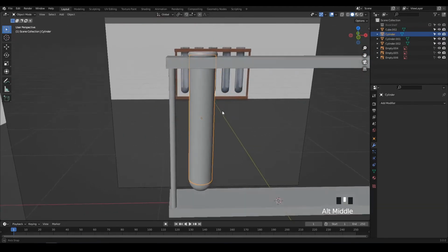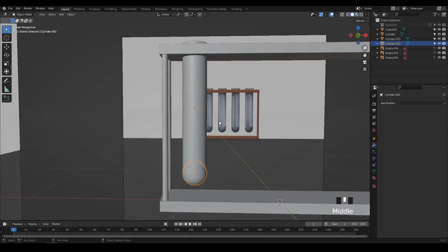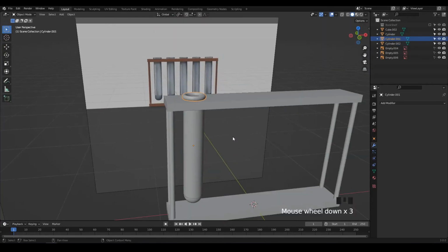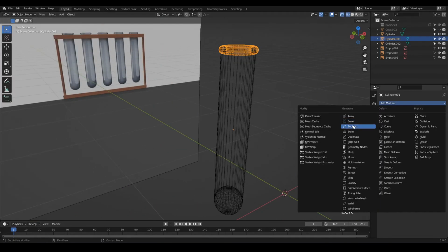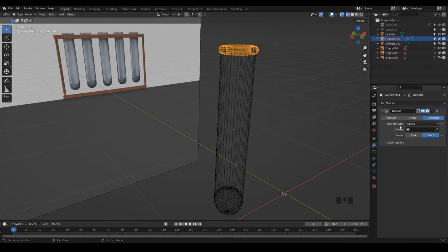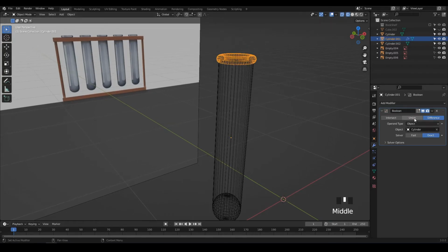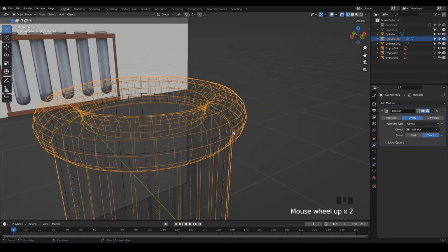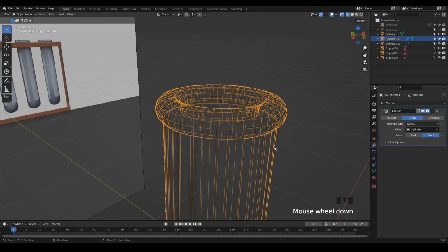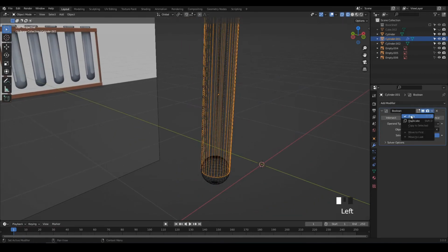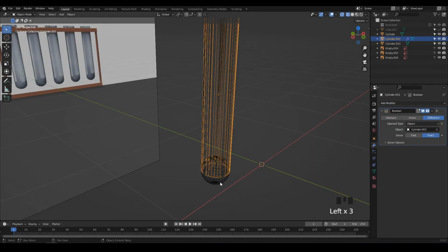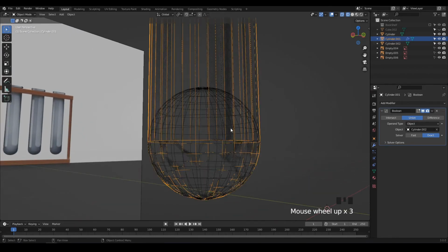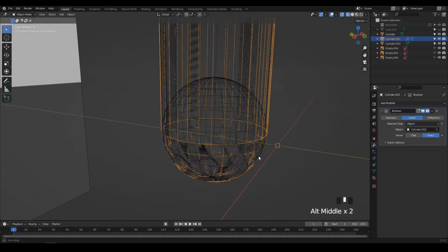What we are gonna do first, you see how this object, I created it the same way we did for the first object at the beginning of this project, like the potion bottles. I'm gonna hide that for a moment. Now, using the Boolean modifier, selecting this object, and choosing union, they are all connected together, because if I apply that, add another Boolean modifier, choose the sphere at the bottom, and choose union, now they are all together.